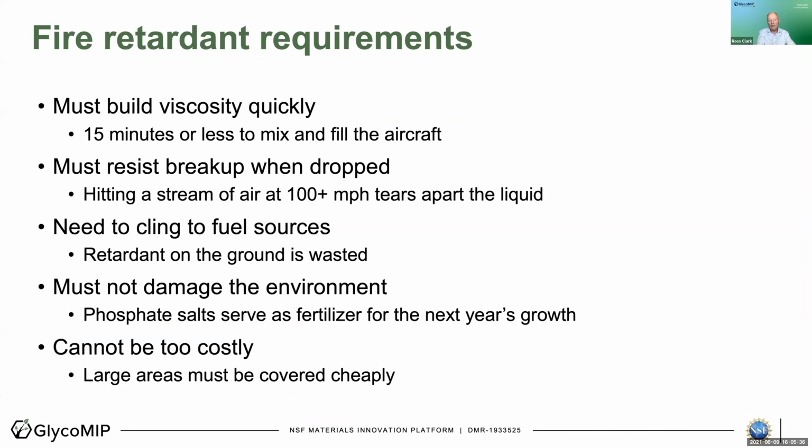So that's a little bit about what it takes for fire retardants. They have to build viscosity very quickly. You can't keep that airplane on the ground for more than 15 minutes. They really want it back up in the air in 10 minutes. It must resist breakup when you drop the thing, as you saw how the air tears at the fluid and tears it apart. It needs to cling to the fuel sources. Anything that lands on the ground, that's wasted. It's not going to keep the brush from burning if it's on the ground.